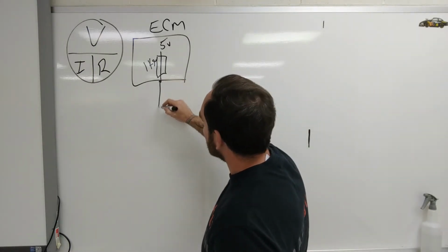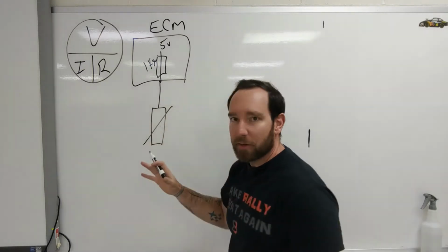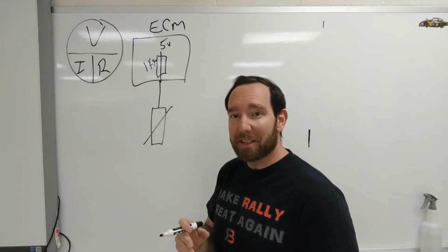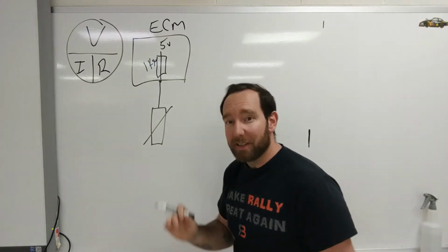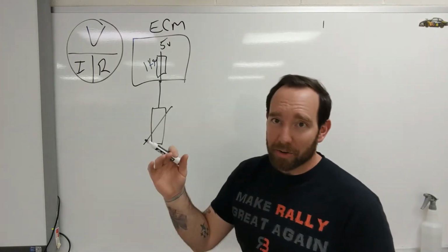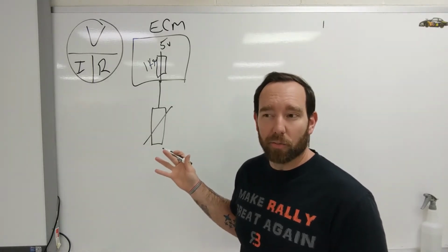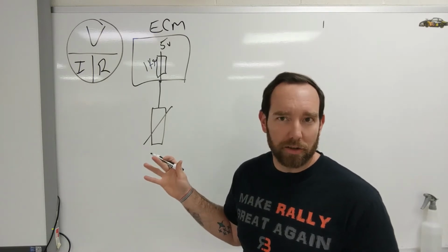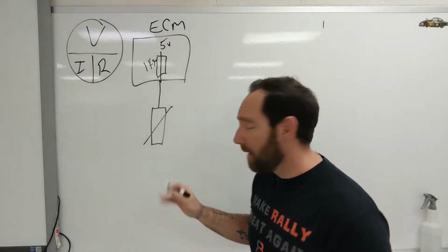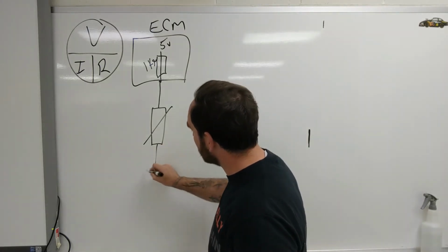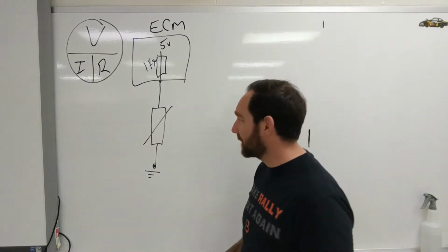All right, so then our circuit continues on to our thermistor, our variable thermistor. In this case, it's PTC. Remember I talked to you about being a couple instances where we use PTC, which means when temperature goes up, resistance goes up. We do see that in exhaust gas sensors. The example I think I used in class a lot was protection devices on hybrid and electric vehicles. Okay, but this is an area that we do see this. Again, it's very simple, okay? All right, and then that, of course, goes to ground, which is the exhaust, right? It's in the exhaust, so the exhaust acts as the ground.